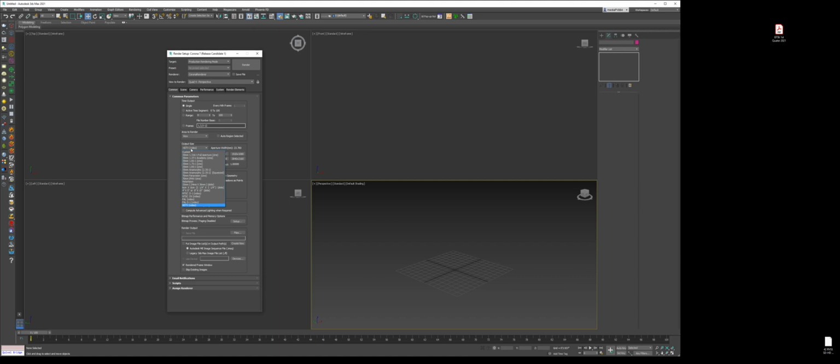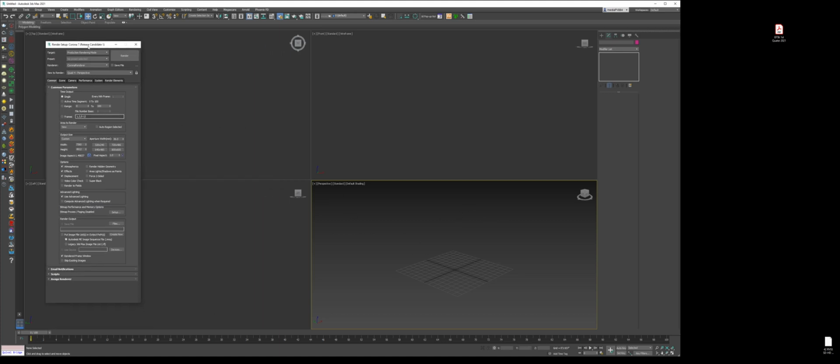And now if you're using a backplate or if you shoot your own backplates, typically if you're full frame, you're at 1.5 aspect ratio. And if you do medium format, you're at 1.333. So what I'll do is 1.5. I'll change that right away, and then 7360 by 4912. That's my D810 backplate resolution. So we'll do that. Make sure that matches up so that when I'm rendering high res for my backplates, it's apples to apples.